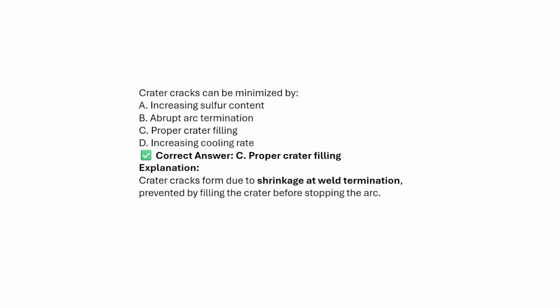D, increase in the cooling rate. If we increase the cooling rate, it will increase the residual stresses, which will also increase the cracking, so that is also no. So the answer will be C, proper crater filling. Crater cracks are due to shrinkage at the weld termination, so they are prevented by filling the crater before stopping the arc.